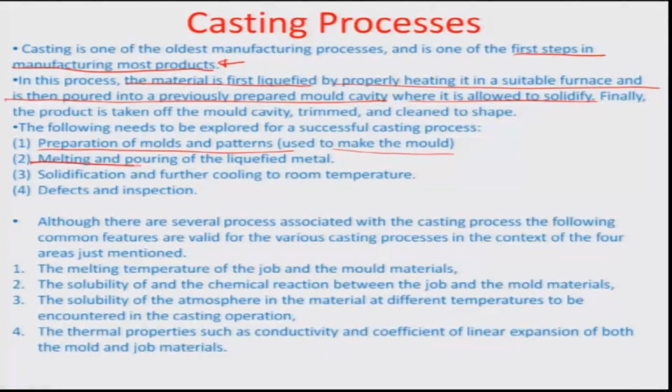So therefore, you need to be able to prepare it with a refractory material. Normally sand molds, green sand molds are very commonly available, because sand is a refractory material which can withstand high temperature and still be strong, so that is why sand is mostly used. And then also you have to melt and pour the liquid metal. So there is a lot which comes into the way of this, because you are essentially passing it through a channel which is also known as the metal runner, and then there is a gate which throws the metal into the cavity where the filling action starts taking place.